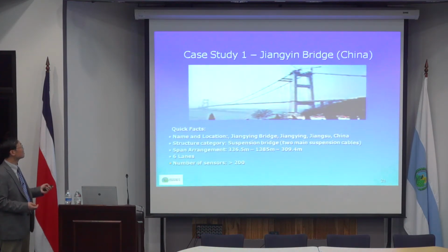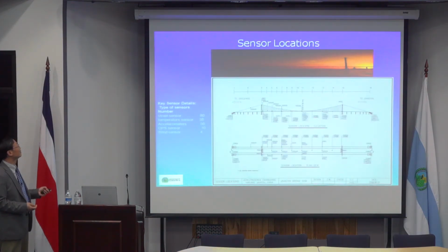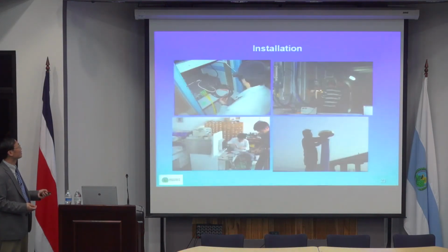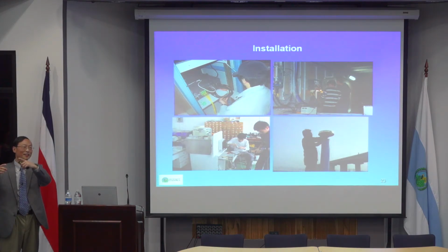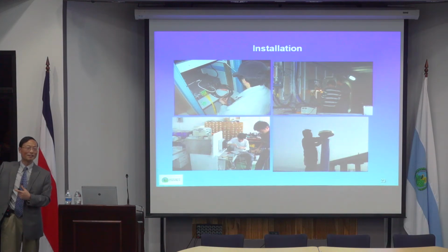These are typical bridges, how many sensors and different types of sensors were installed, and the sensor locations, and basically these are the design sketches. Typically these sensors will have wireless collection, because the data is collected continuously. So they have a central collection server, and this server will use the internet or Wi-Fi type wireless to go to a remote receiver.